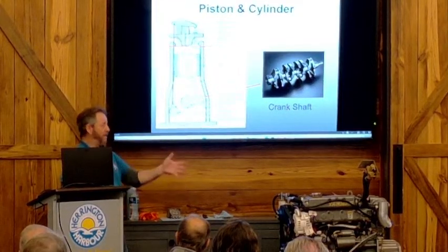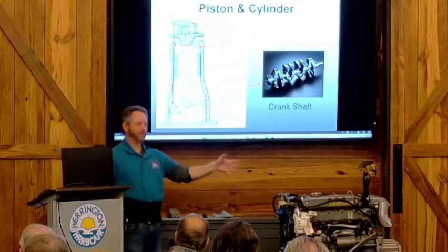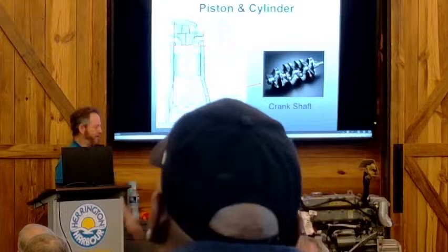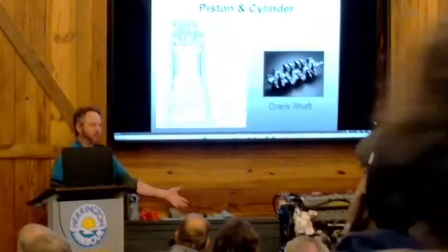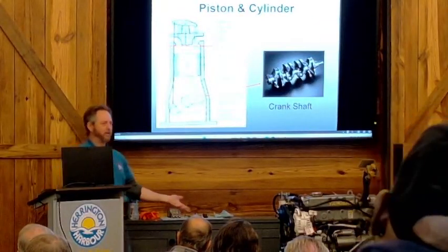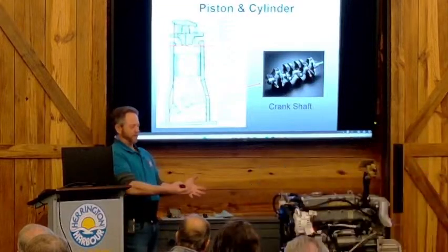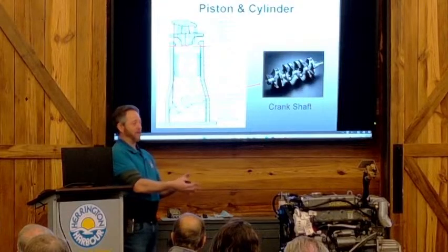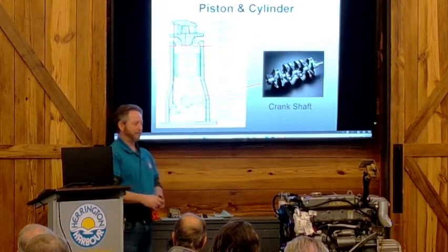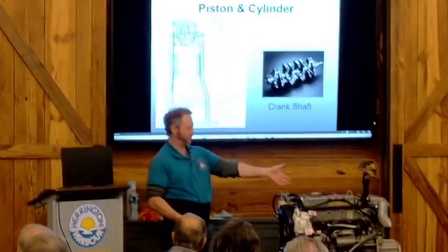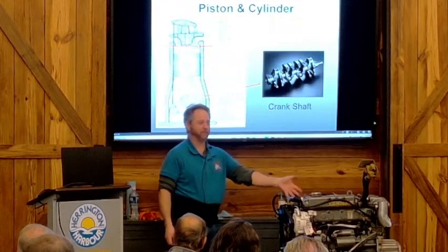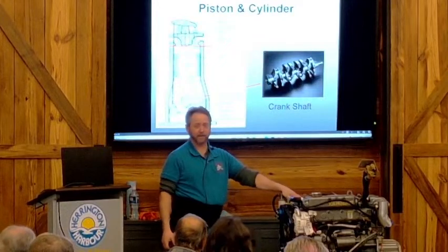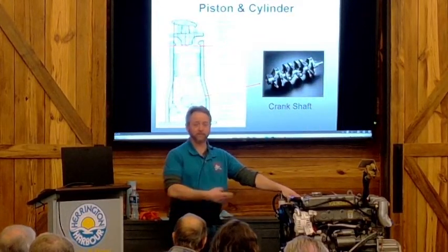And that's the only thing that's protecting our engine, our expensive engine, from deteriorating. So changing our oil every 100 to 200 hours or once a season is a fairly inexpensive service compared to buying a new engine. So this engine, I would assume, well, you can't get this engine anymore because it's now an electronic engine, but I would assume it's probably about 18 grand to 21 grand to replace this engine.